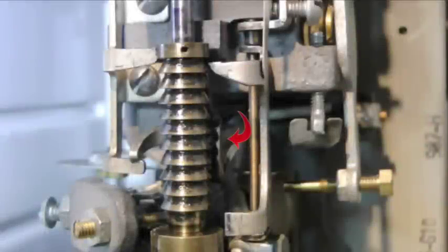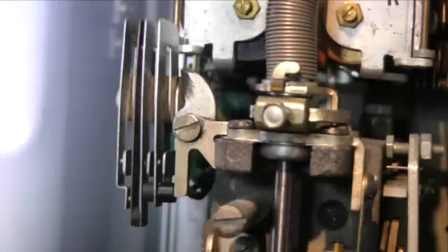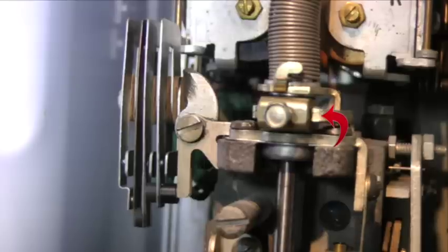Attached to the end of the vertical armature is the vertical pawl. When the vertical armature operates, the pawl engages a tooth of the vertical ratchet and pushes it upwards one step. Since the shaft is attached to the vertical ratchet, it also moves upwards by one step, as does all apparatus attached to the shaft. This includes the normal pin and clamp assembly, which frees up the off-normal finger.